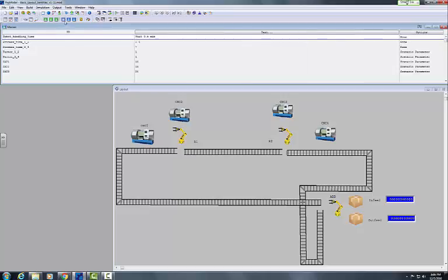The other important thing which we have used in the simulation model is the macros. So what macros essentially do is they have a placeholder in the sense that instead of having to input the processing times for each one of the CNC machines separately or for each one of the robots separately, we can define one macro for all the entities together and input the value here.